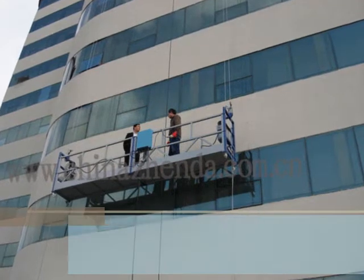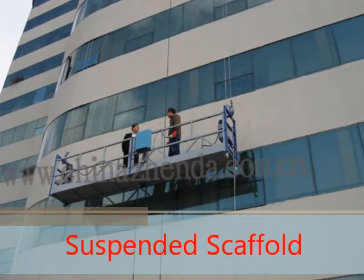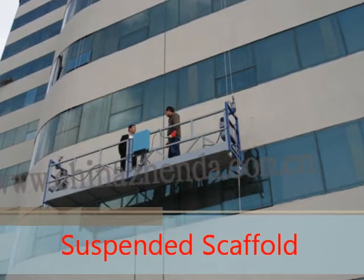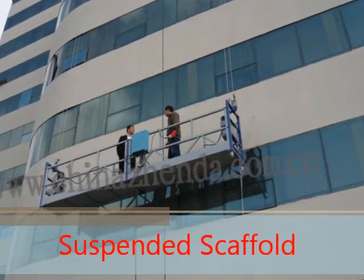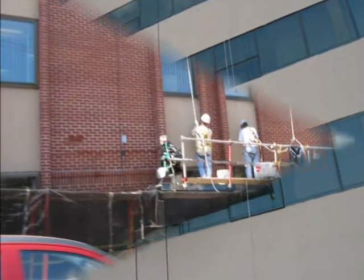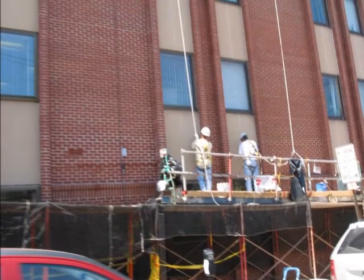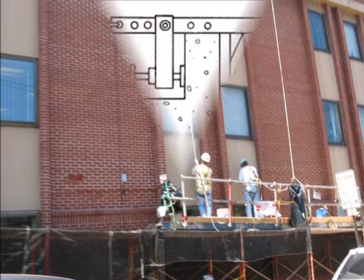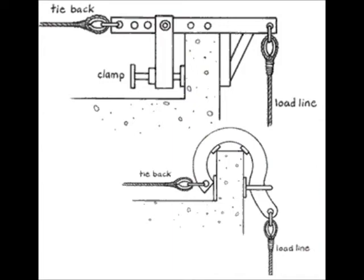Next we will be discussing suspended scaffolding. Suspension scaffolding is a platform suspended by ropes or wires or other non-rigid means from an overhead structure. As seen in this picture, these scaffolding must be secured and or tied off to prevent swaying. Their support devices must rest on surfaces that can support 4 times the load.